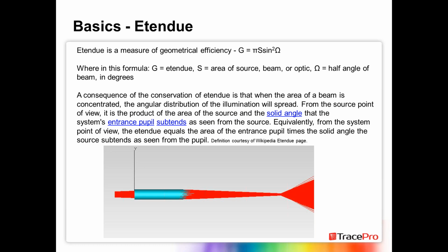So this is something we're going to use as we go through the designs and the examples that I have in this system, because we want to take advantage of that when we may have a very nice output that we'd like to have, but we want to be seen from a lot of different angles. Say that we're in an automotive application and we have a dashboard, and we have an icon on that dashboard that we want to light up, and we want both the driver and the passenger to see it. So what we're going to want to do here possibly is concentrate that light pipe, so when the light does come out towards the visual aspect of our target, our driver and our passenger, it gets seen by both of those people. So this is something we can use and keep as an idea, using étendue for this type of thing.